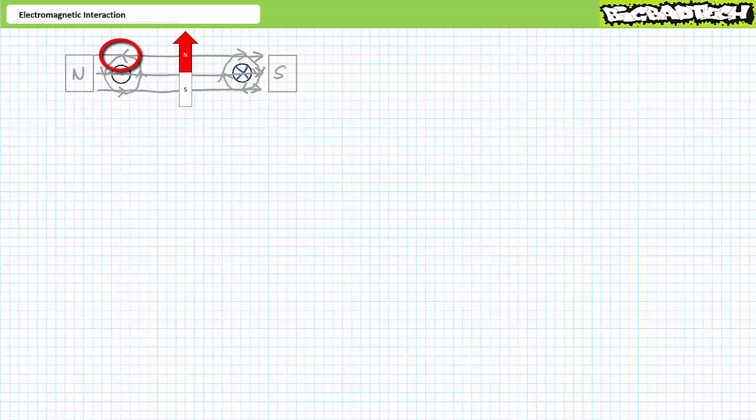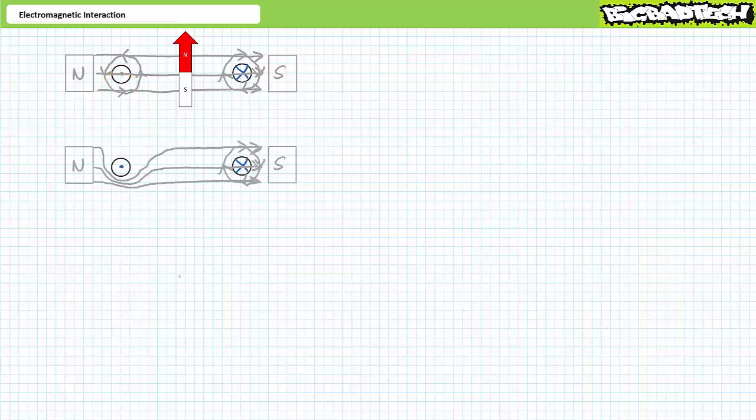Note the magnetic field on the top of the left-hand conductor is opposing, whereas the magnetic field on the bottom of the left-hand conductor is aiding. These magnetic fields coalesce such that there are more lines of magnetic force on the bottom and less on the top. The unified magnetic field below the conductor acts to push the left-hand conductor upwards.